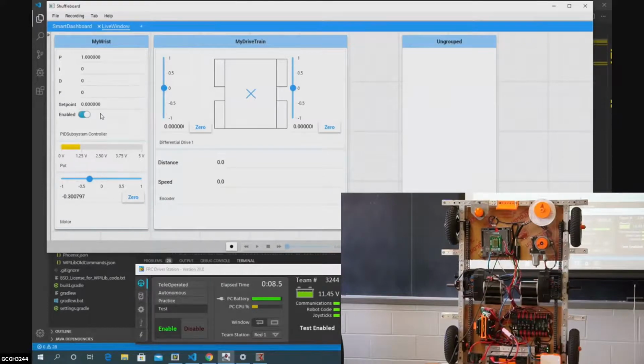And you can see the set point currently is at 0 and it's locked in up and down. If she puts 90 in there, you can see it is trying to close and go to 90. And as I get closer, it's hunting for that. So I'm pretty happy right now that everything is working, and I am ready to mechanically attach my output device to my motor because I can see that it is trying to get there, and we're going to tune our PID. So if you can disable that for a moment.